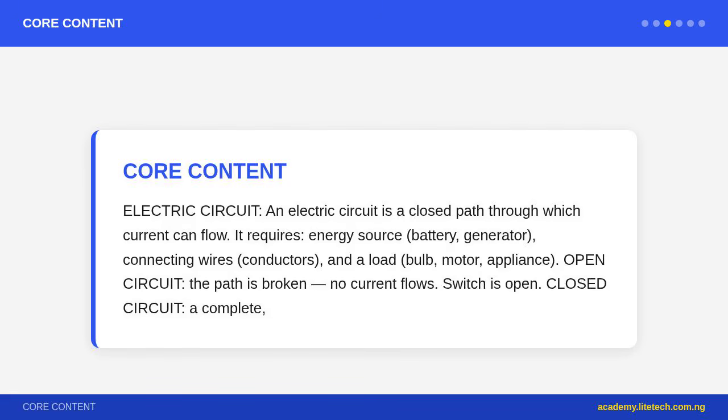Conductors and insulators. Conductors allow electric current to flow freely, they have free electrons that can move. Examples: copper, most common wire material, aluminium, iron, steel, silver, gold, graphite, salt water, human body, wet materials. Insulators do not allow electric current to flow, electrons are tightly bound. Examples: rubber, plastic, glass, dry wood, dry air, ceramic, cotton, PVC. Insulators are used to coat wires to prevent accidental shocks and short circuits.